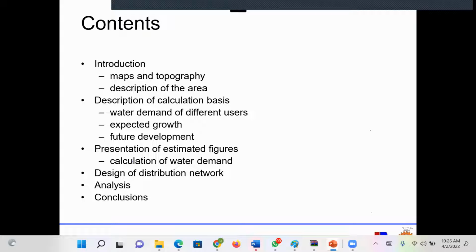So you must have a place you're going to take that water from, which could be groundwater, surface water, an artesian well, a long distance water supply, or rainwater. So these are 4 different sources of water. So your job is to get the source, then you either put it in a holding tank, which is still a source, and then you take it to an upper reservoir where you can supply the water by gravity.